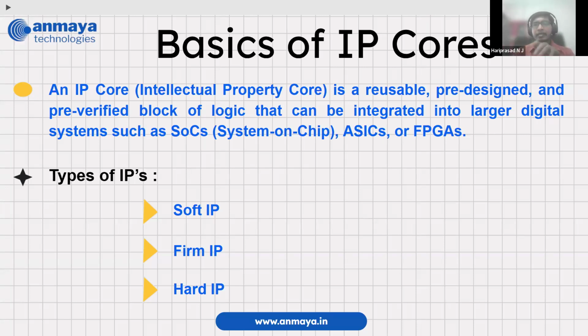Usually now, if you see Zynq SoCs, we will have a hardcore ARM SoC, a hardcore PCIe core, Ethernet cores. Basically, every hard IP is going to add some contribution towards the cost and size of the chip, right? So we cannot put everything as a hard IP.